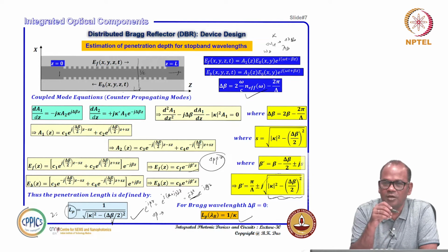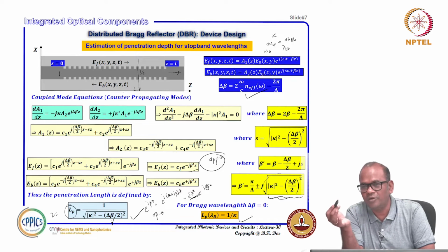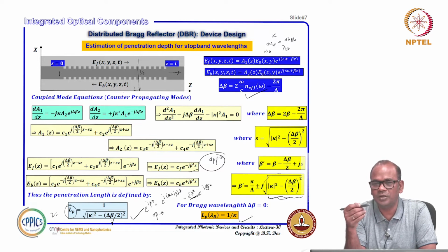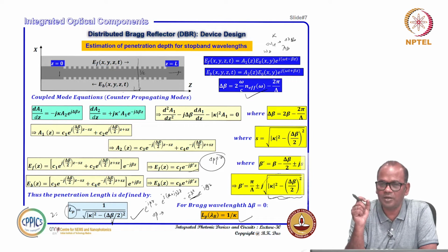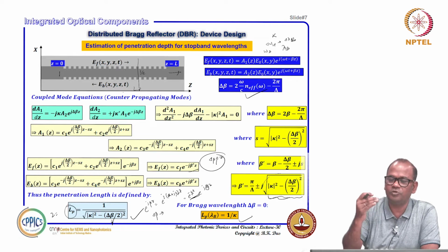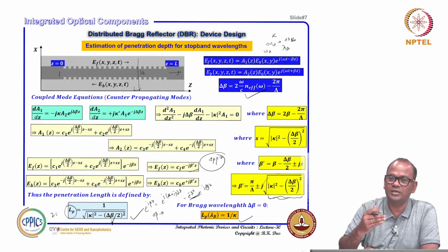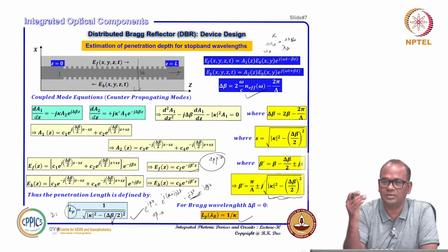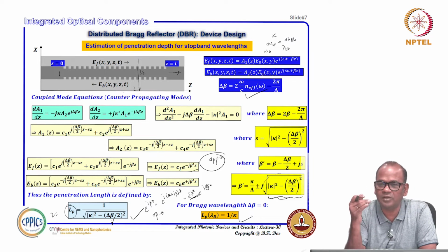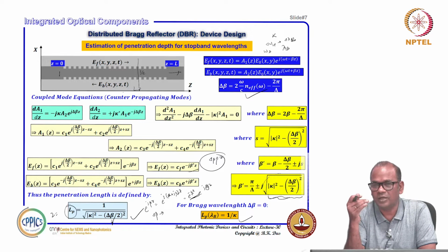That is how you get conductor, semiconductor, dielectric, where the band gap defines it. If there is no band gap, the conduction band and valence band almost overlap, that is a metal. If there is some gap between the two bands, it is called a semiconductor, and if the bands are widely apart, there is a large band gap, then that is called a dielectric material.